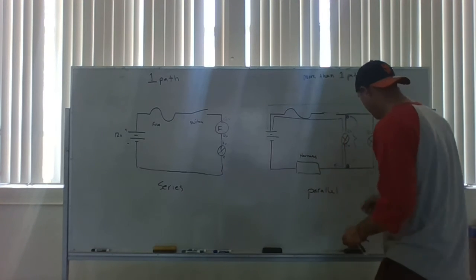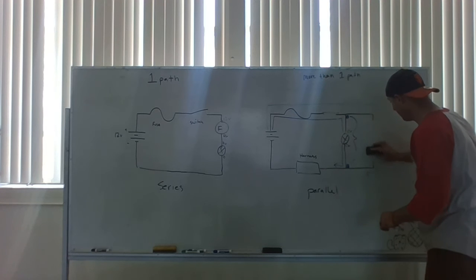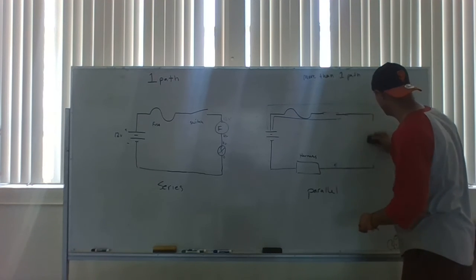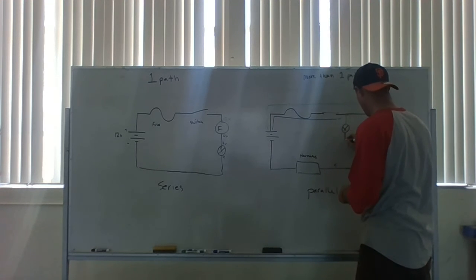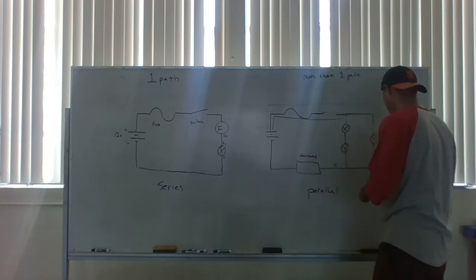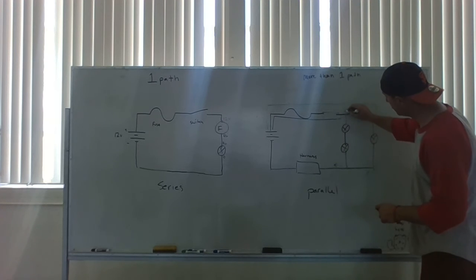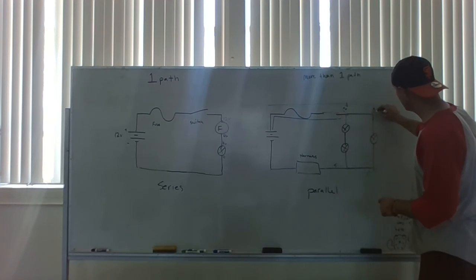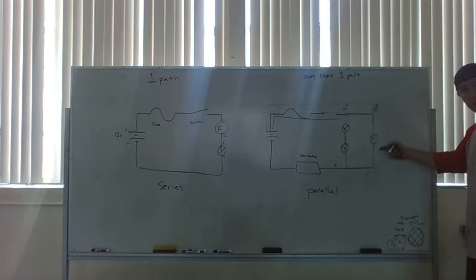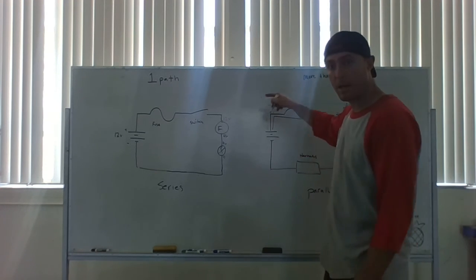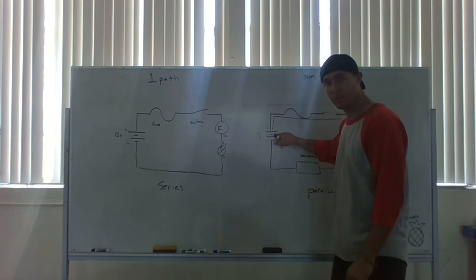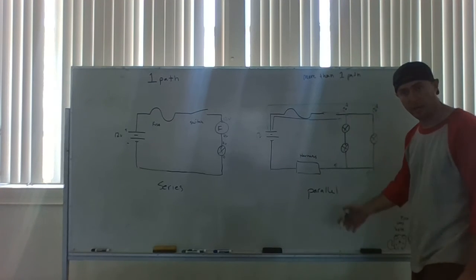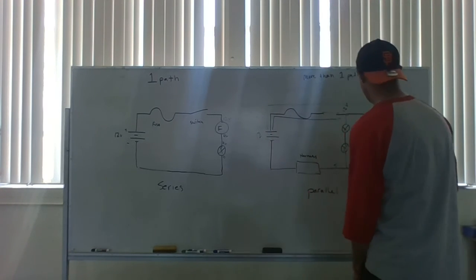All right, so back on this example over here, let's say down this path, remember, at the branch, at this junction, I have 12 volts and 12 volts. I've not gone through a load yet. Therefore, I'm still on the power side of my circuit. And so I'm expecting whatever my source voltage is to still be there because I haven't used any voltage yet.